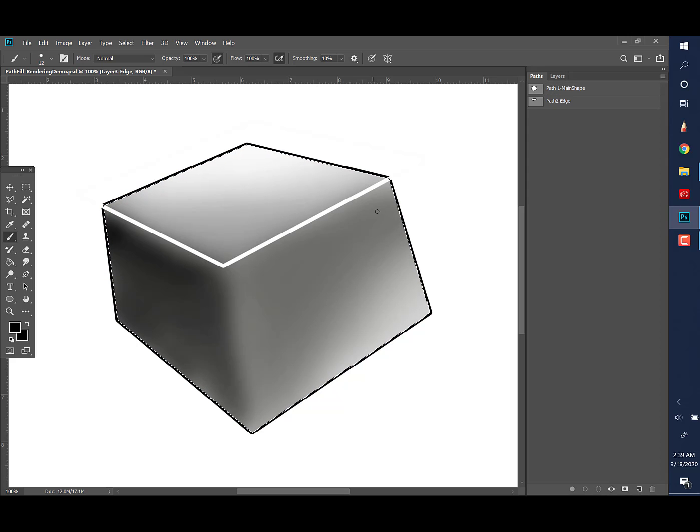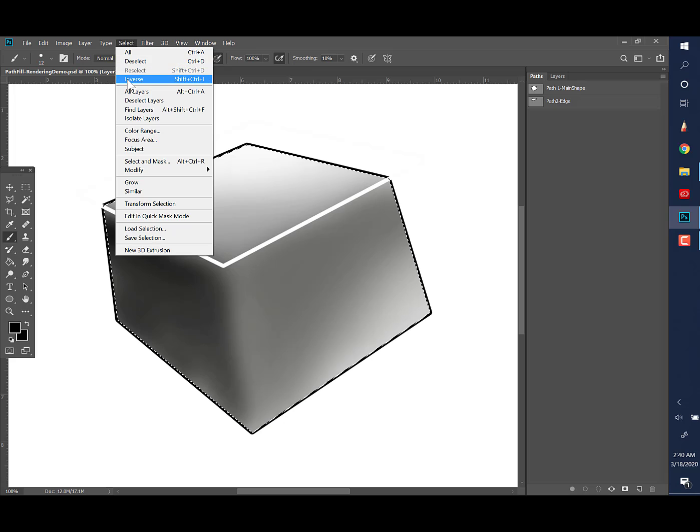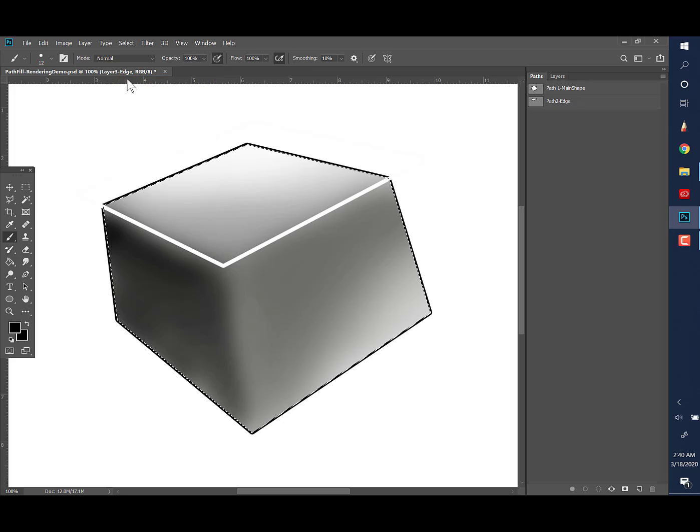Okay, you see the marching ants? Now, I want you to keep an eye right here on these corners. You see where there's a black and white line happening through there? Now, you're going to see some transformation going on. So we're going to engage the selection tool, and we want to invert it and then delete all of that material on the outside of those marching ants. So let's go to select, inverse, okay?